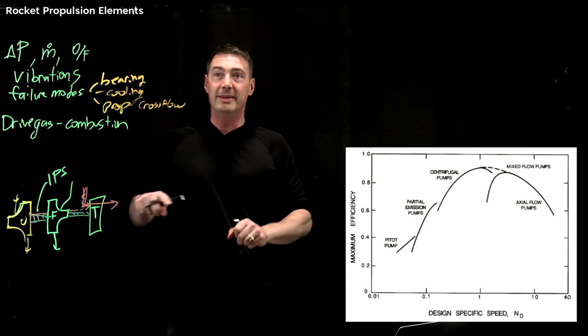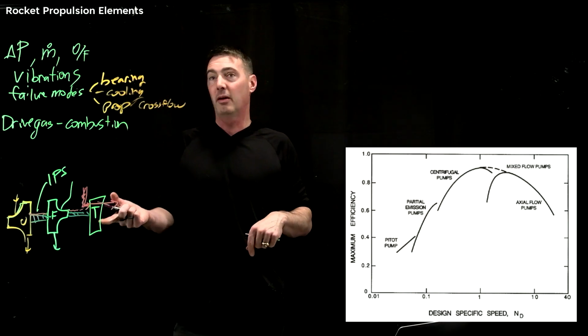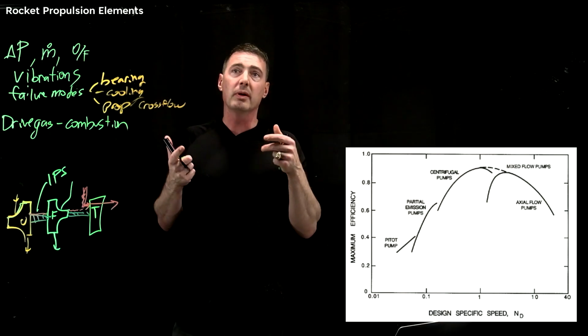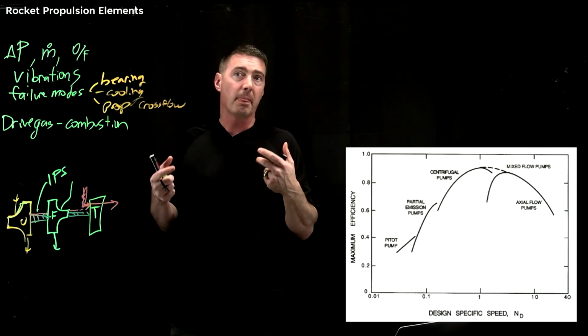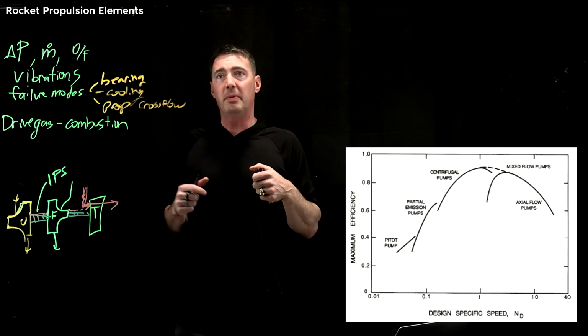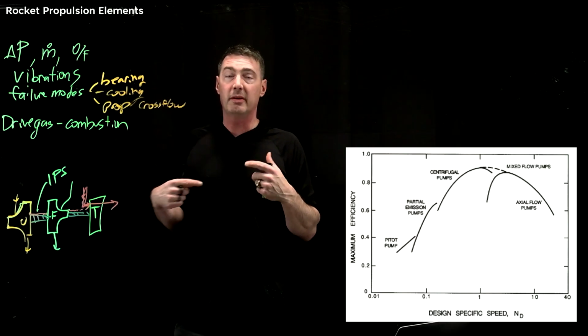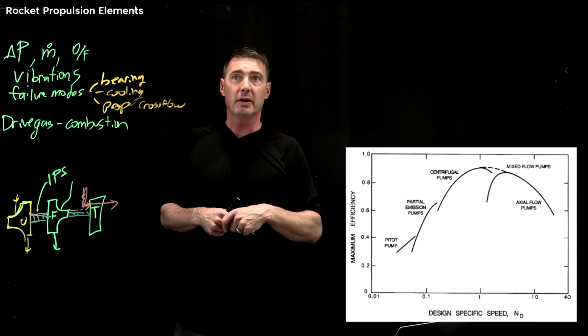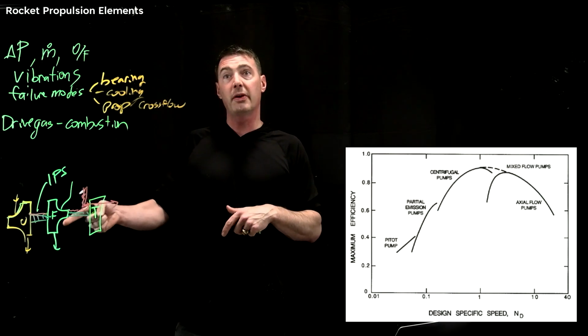And that is what is keeping the fuel and ox away from each other. Some designs usually have some sort of gas on board, nitrogen or helium, that they're using. Other people just try to drive enough of a labyrinth seal where that mode is really, really reduced, so you're not going to see it. So there's a lot that goes into this.